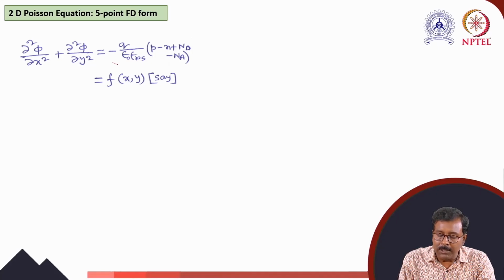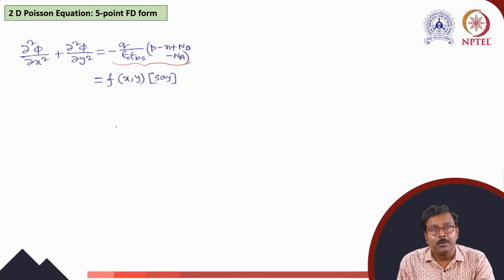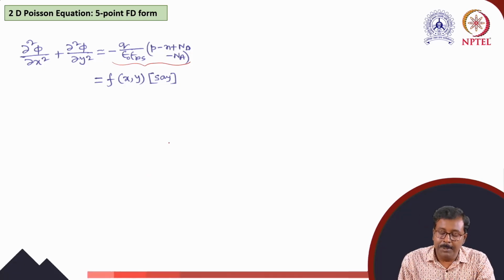This total function is a function of x, y, because it is also position dependent. All the nodes may have different charge, different donor concentration, acceptor concentration, etc. So in general, it can be written as f(x,y). If f(x,y) is 0, this becomes the Laplace equation, where the right hand side will be 0.